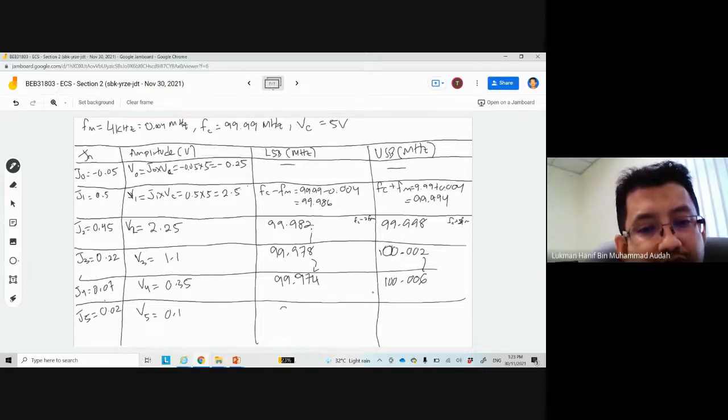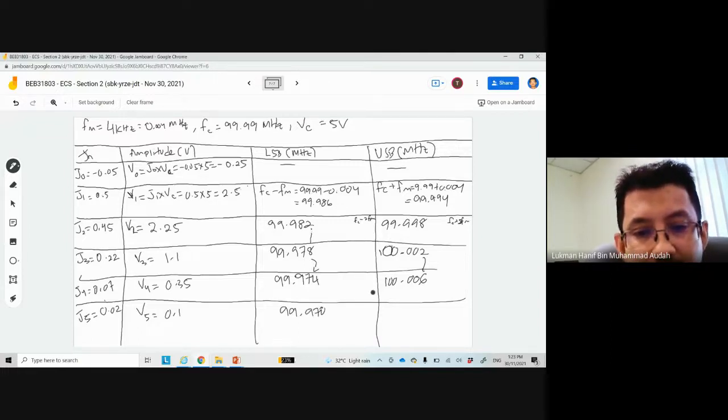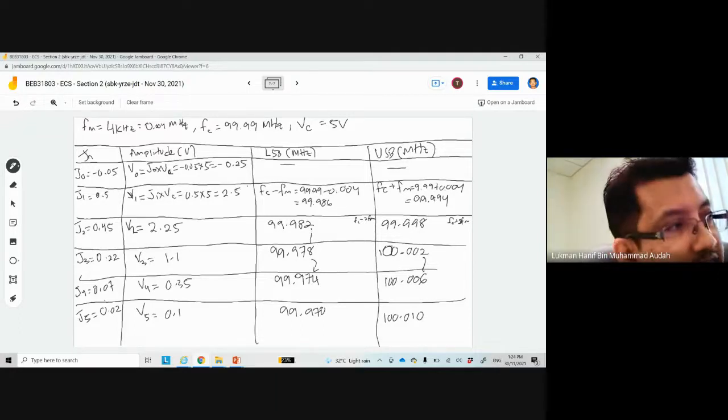Over here is 99.970, FC minus 5 FM. Over here is FC plus 5 FM, which is 100.010 megahertz. Then what? Then we need to draw.